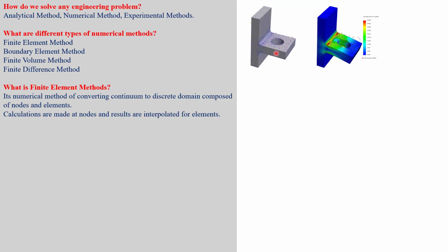You can see this is the model, which is meshed. At the back end we have the boundary condition that is fixed, and we can apply the load here on the top. This is going to deform, and you can see this is the von Mises stress. It is on the elements, not on the nodes. If you want to extract the nodal stress, that is also possible.